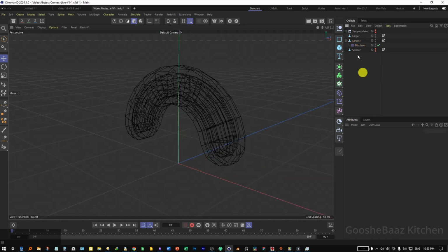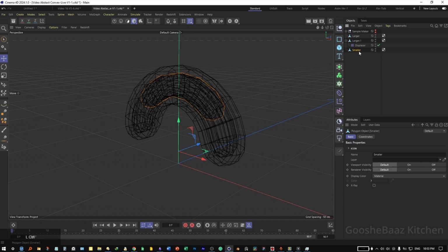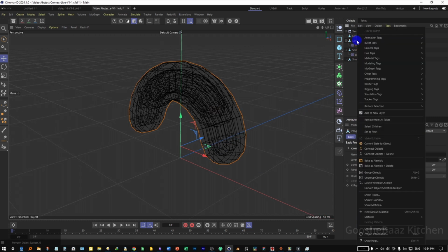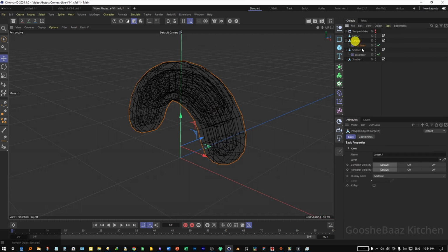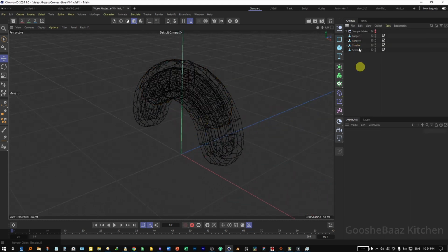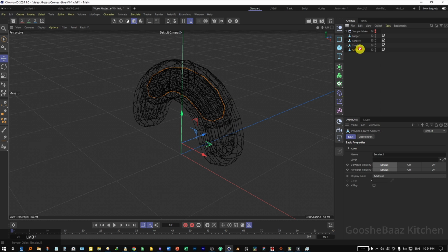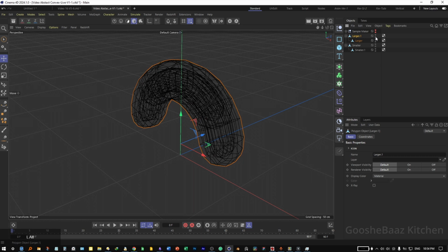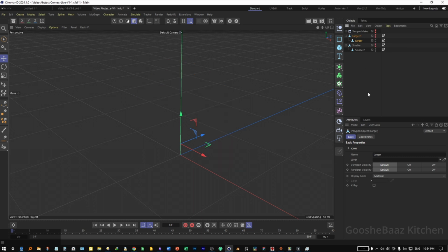That's okay for now. Let's also enable the smaller one, duplicate this displacer on one of them. Connect object and delete on the object with displacer deformers. Connect object and delete. That's good for now. Let's put the smaller ones into their shields. This is the smaller, put it here. Let's hide the bigger ones and make the visibility for the smaller ones to be on.